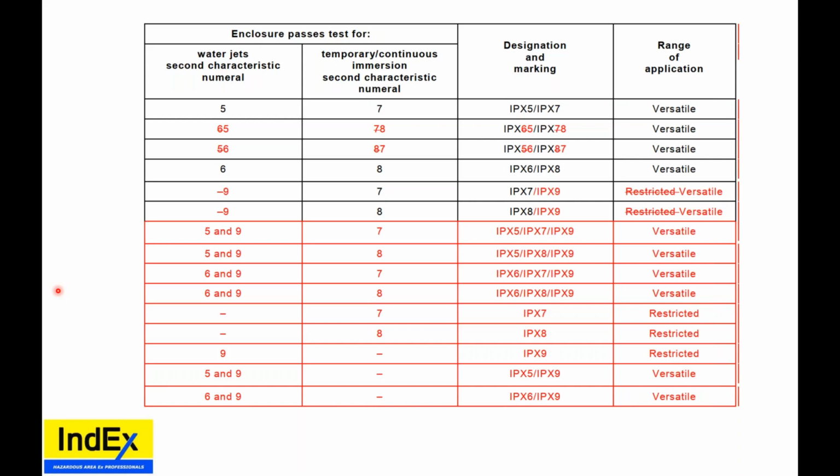Some manufacturers only tested their equipment for 3 minutes at IP66, and it has failed within Australia. Because when a cyclone comes through with 300-kilometer-an-hour driven water, it's going to fail, which then negates the EEHA protection technique: water inside, arcing, sparking, a potential source of ignition. Is IP54 enough?